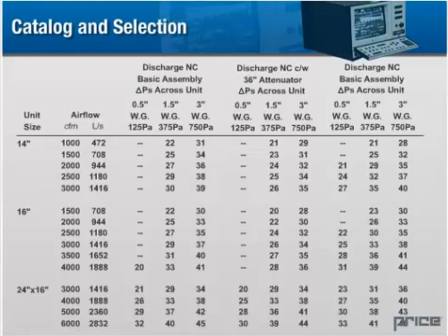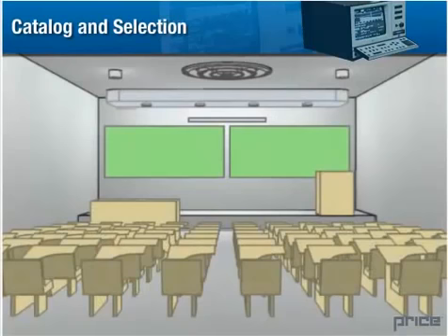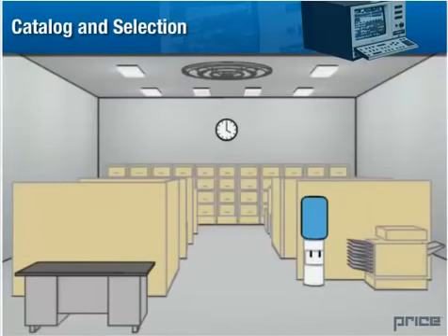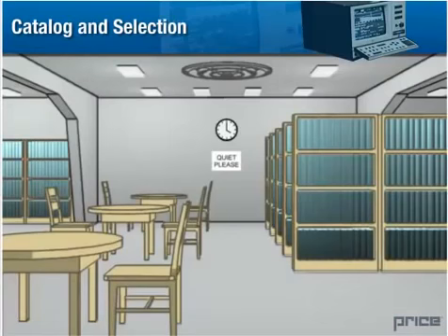These figures appear in the catalog in typical selection guides for terminal units. Similar data appears as performance data for GRDs. Note that when it comes to HVAC products, a device with a given sound power level may be suitable for some environments but not others, depending on the reverberant characteristics of the room and the client's needs.